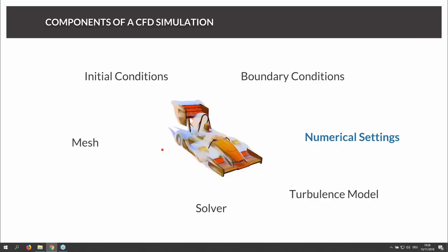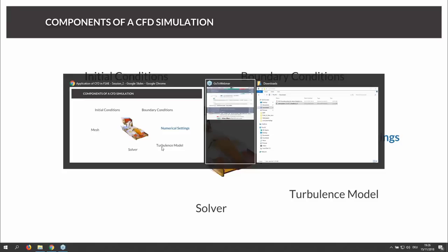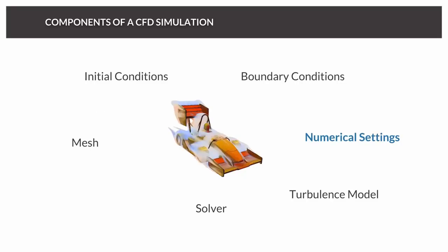Yes, also a very important aspect is the choice of the right numerical settings. Since we're using numerical schemes and numerical math to solve these problems, all those algorithms have some settings. Some of them are simple to understand. For example, relaxations are controlling how aggressively you are changing your next results for the iteration. But there are some others which are more complex to understand.